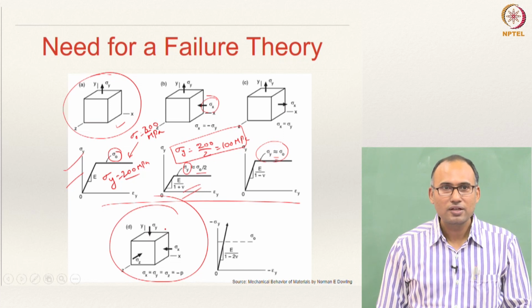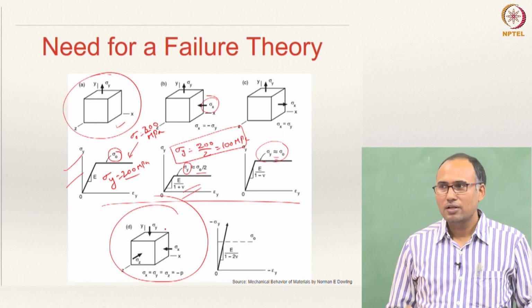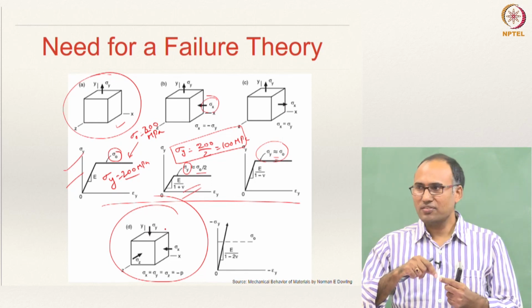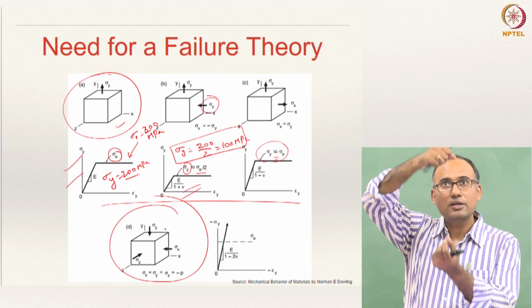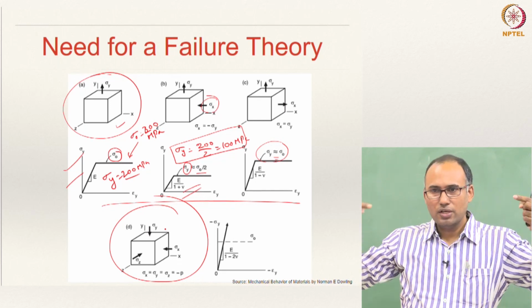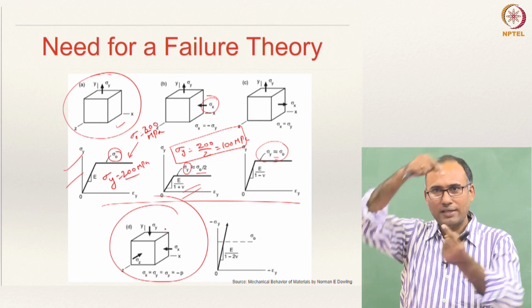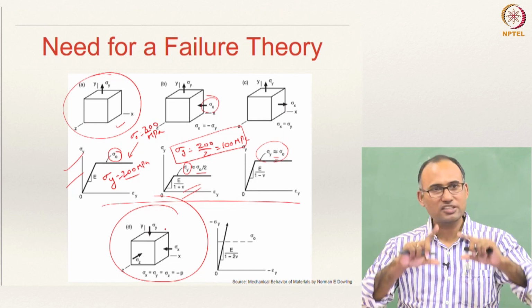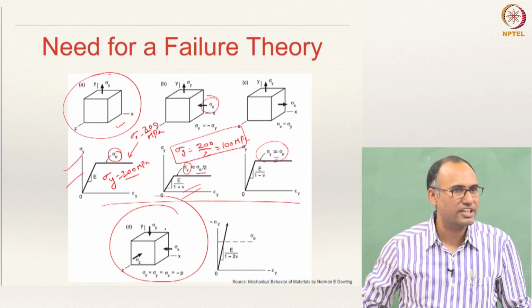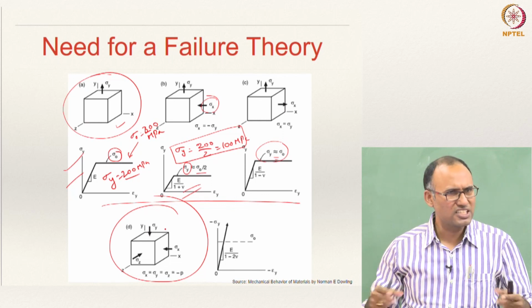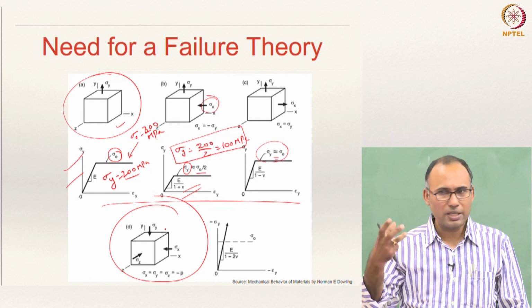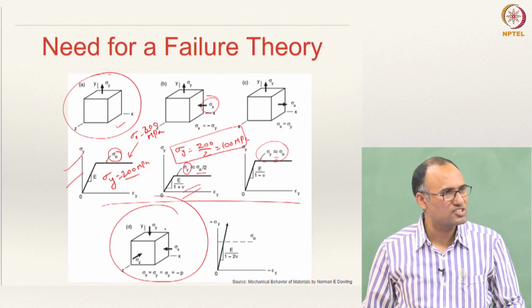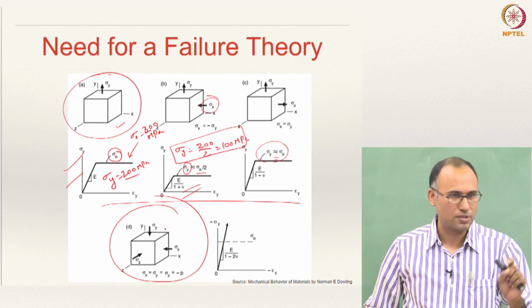And these three things are one, and the fourth one is even more interesting. You have hydrostatic stress, which means that in all three directions, if you are applying compression in this direction, in the direction of y, xx and zz you also apply compression. That means the normal stress in all three directions is the same, and that is what is called the hydrostatic state of loading. This is typically what you can generate by keeping a specimen underwater. If you keep it underwater, the specimen is usually subjected to a hydrostatic state of compression.